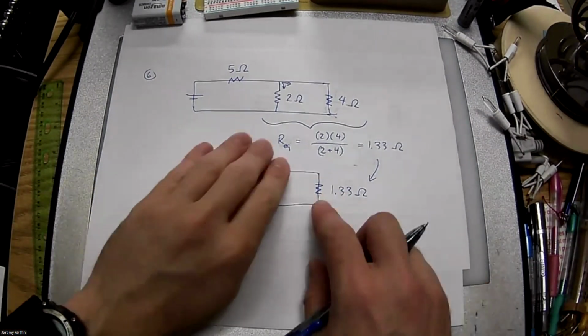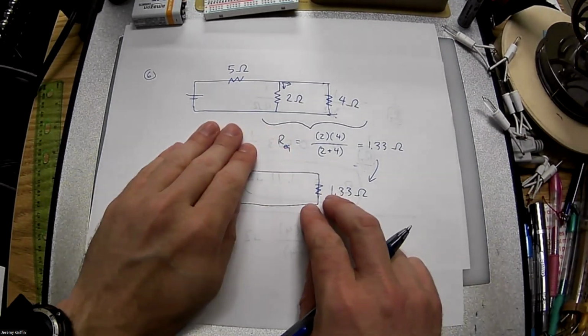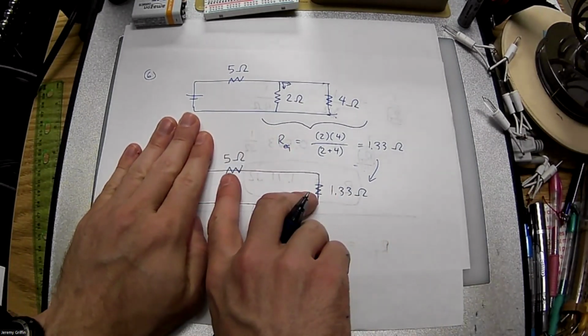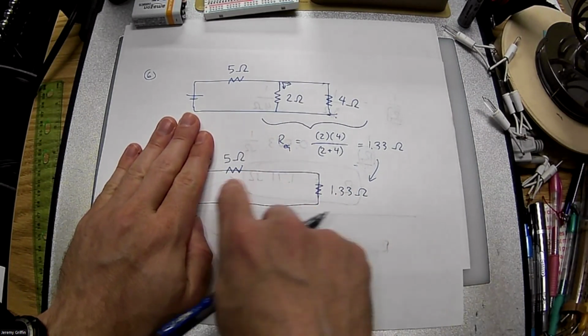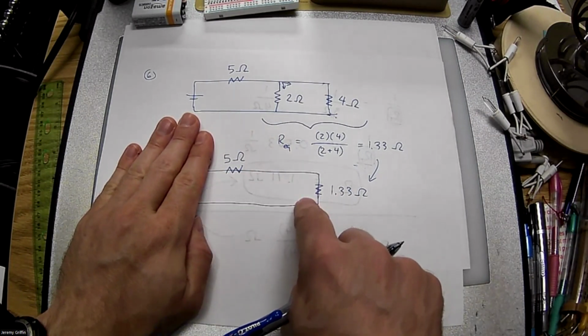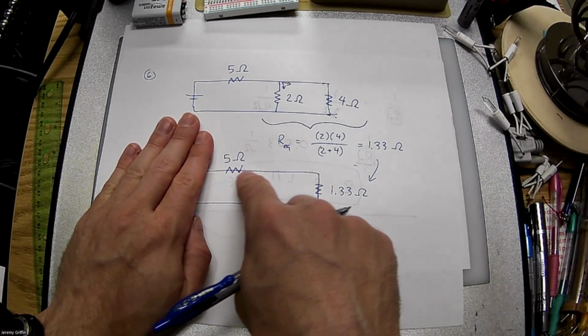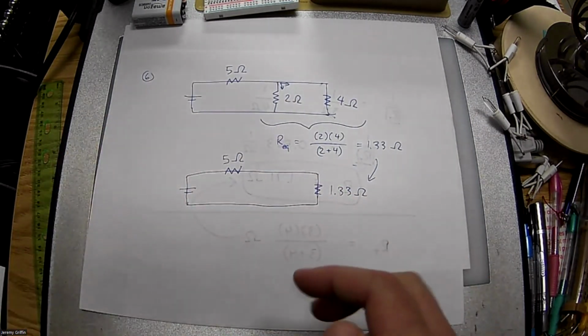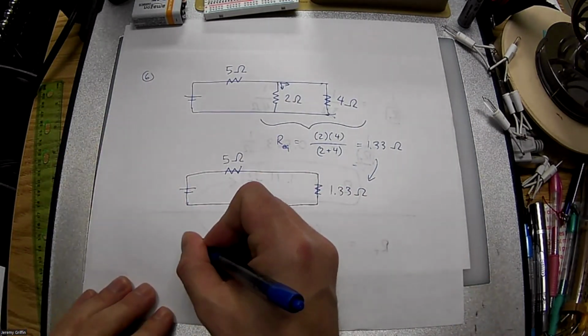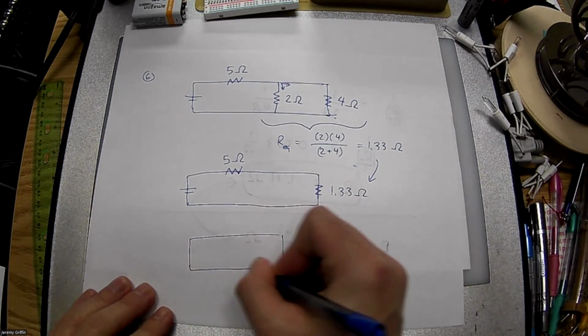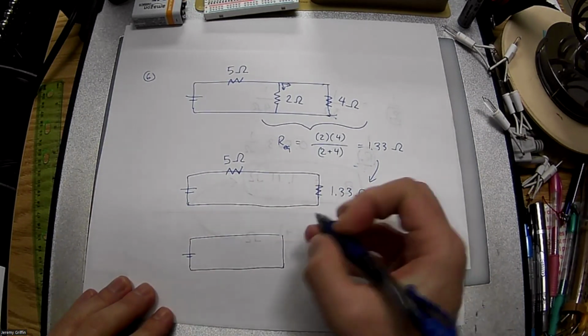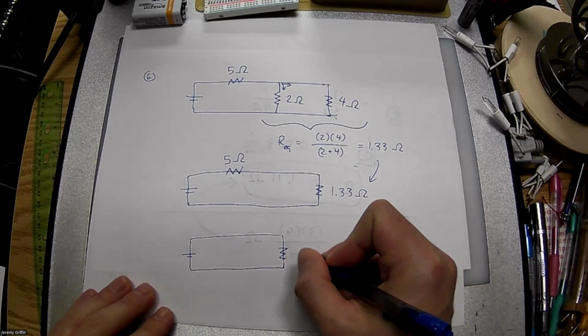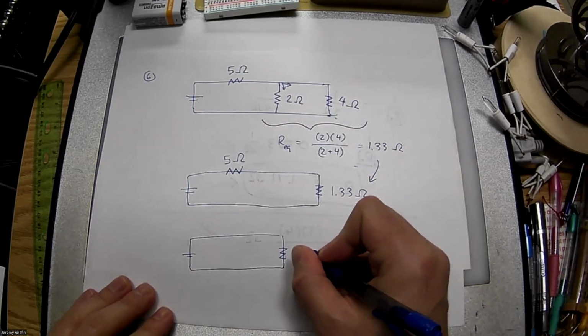All right, so we're picking up from that part of the story. We're going back towards the voltage source. Then I'm going to run into that resistor. Now these resistors are in what, series or parallel? Series. There's only one street. It's sequential. That's series. Therefore, can I just add them up? Yep, that's it. So now my equivalent circuit looks like this. 5 and 1.3 is like 6.3.